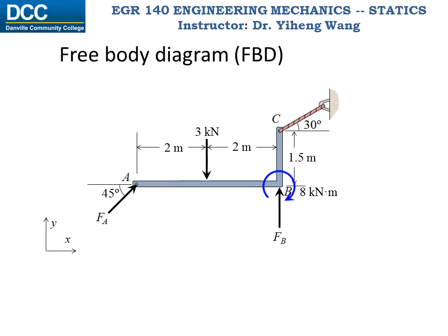Lastly, the cable at point C allows all motions except for when the member wants to move away. Therefore, the force of the cable is a tension force that pulls the member. Keep in mind that the force associated with the cable support is always tension force that pulls. You can imagine trying to use a cable to push. Now, the free body diagram is complete. We have 3 unknowns, Fa, Fb, and Tc. And we can write the 3 equilibrium equations and solve for all of them.